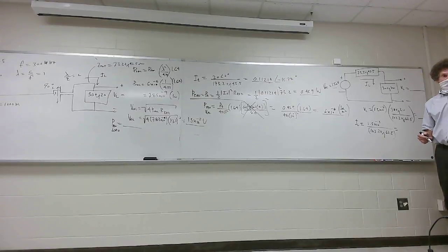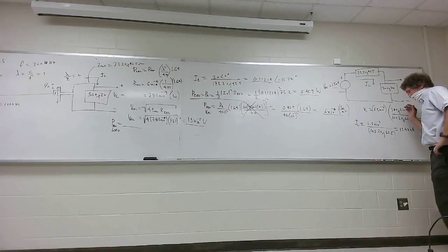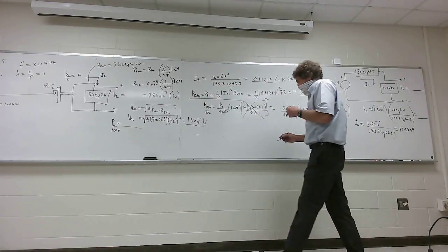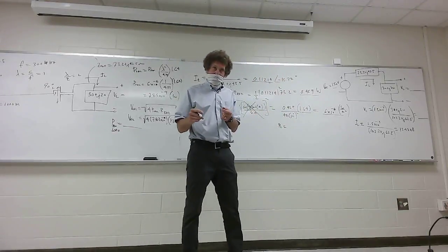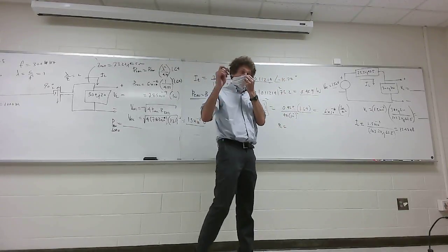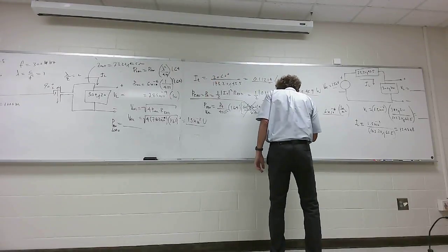Okay? 12.43 microamps. Leave it as that. How much power is received at the load? Don't worry about the angle. It's one half of the magnitude of the current squared times the real part.